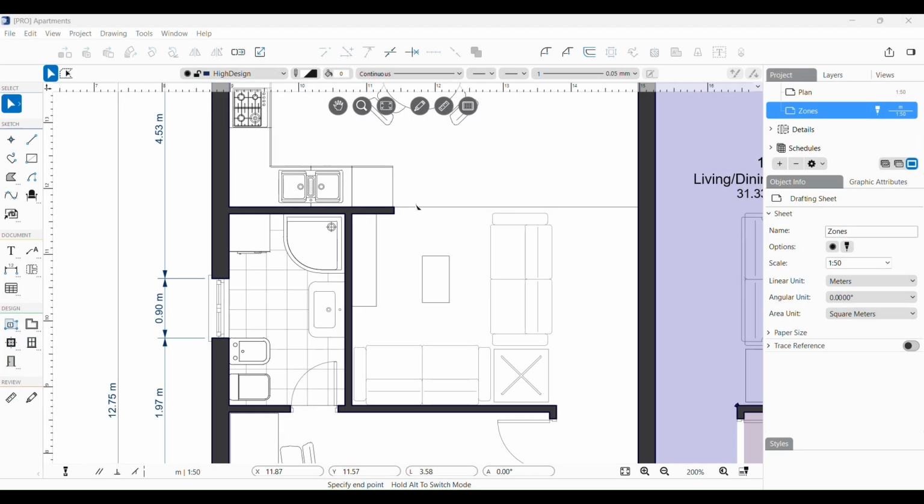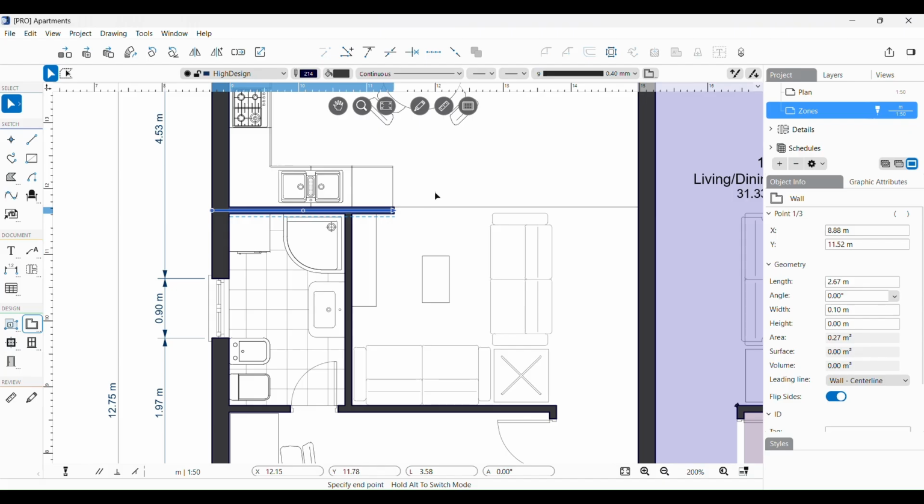The arrow tool is essentially an all-purpose editing tool. Most of the tool-specific editing actions, such as resizing a line, moving a polygon, stretching a wall, or editing a text, can also be performed with the arrow tool. Only selected items can be modified by the arrow tool.